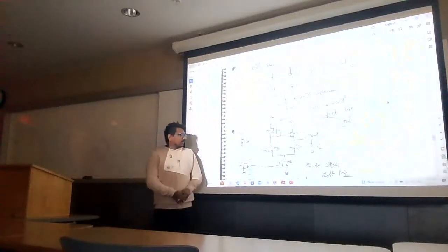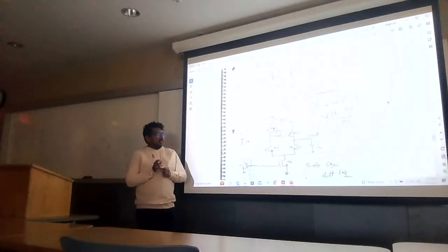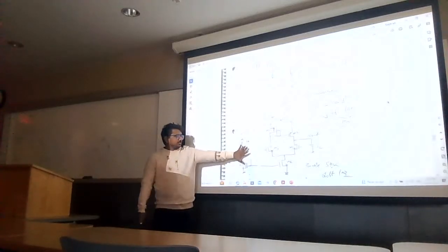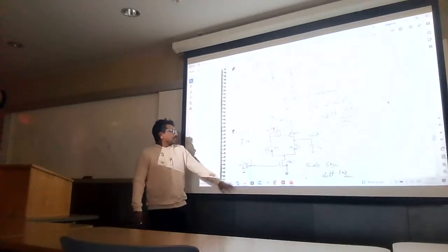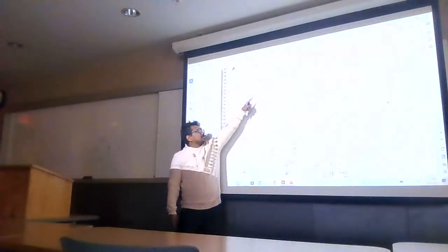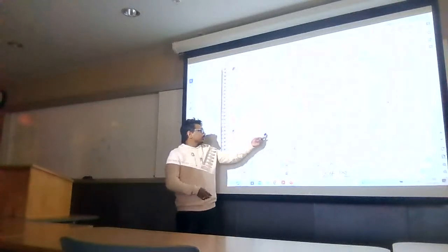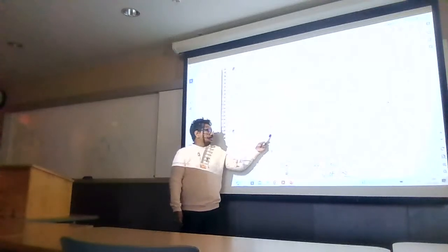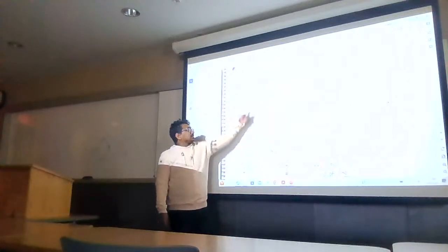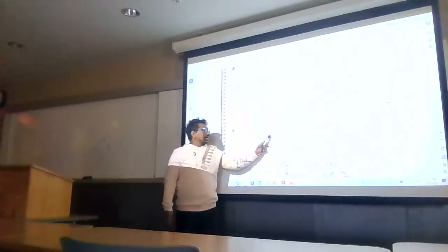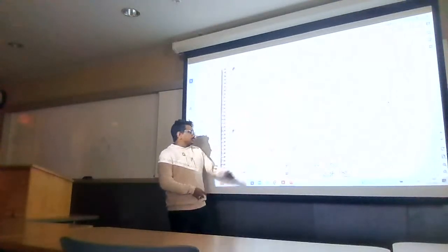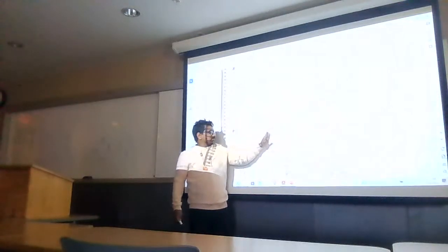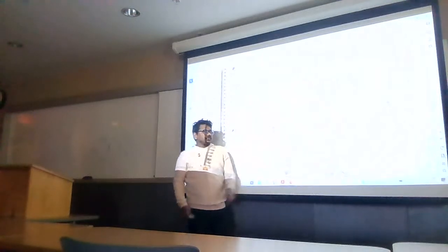Now in practice, how can we design this one? There are a couple of structures. Let's say this is one of the most common structures. Now we have to design this I1 and I2, right? For it, you can see there are current sources. So this transistor should be operating in saturation, then it can work like a current source I1 and I2. If you consider only this structure, it's a current mirror. Just this M1 and M2, it is a current mirror.